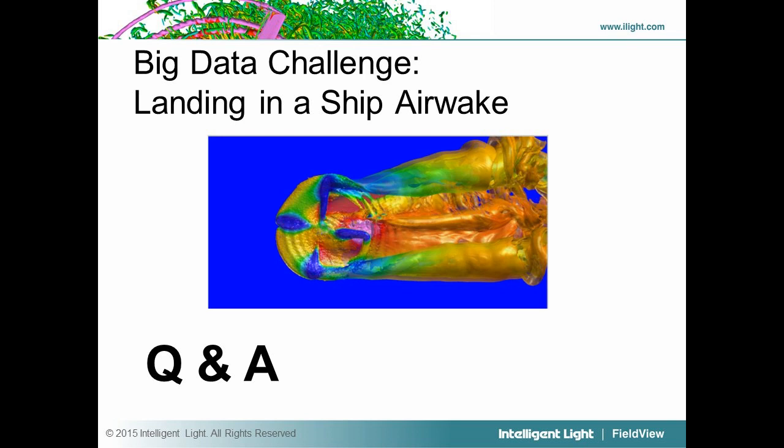and control surfaces. You can define control surfaces using mesh deformation, or you can do it with overset as well, and obviously it has overset. So you can do control surfaces using overset, or where you have a plane that you define with a sliding interface, and then you deform your flap up and down within that sliding interface. And also you can have a region embedded in another region with the whole interface between the two sliding, and it does conservative interpolation between the two.